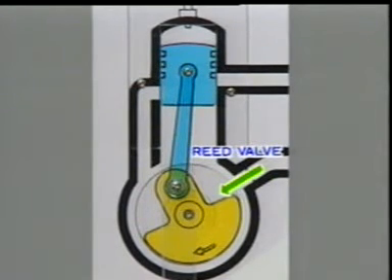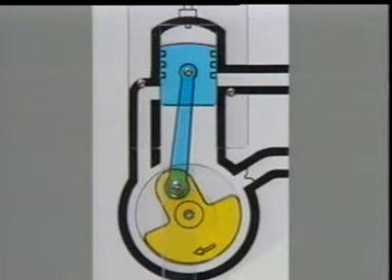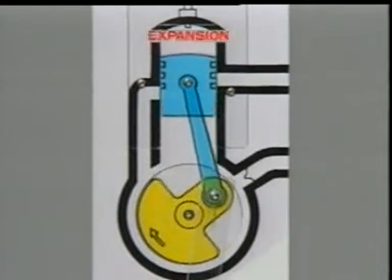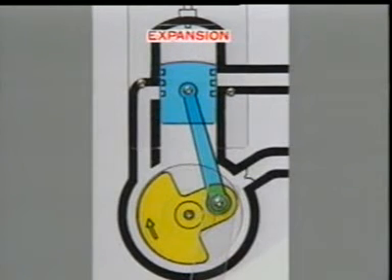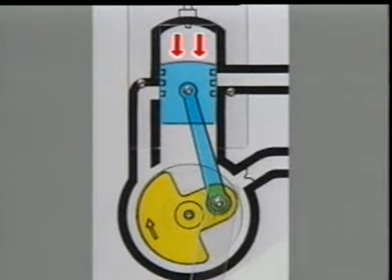The mixture that was compressed as the piston rose is ignited by the spark plug just before TDC and burns instantly, creating gases that expand. The expanding gases create pressure that push the piston down hard, creating the driving force of the engine.